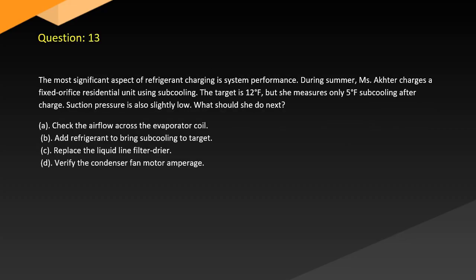Question 13. The most significant aspect of refrigerant charging is system performance. During summer, technician Acta charges a fixed orifice residential unit using subcooling. The target is 12 degrees, but she measures only 5 degrees subcooling after charge. Suction pressure is also slightly low. What should she do next?